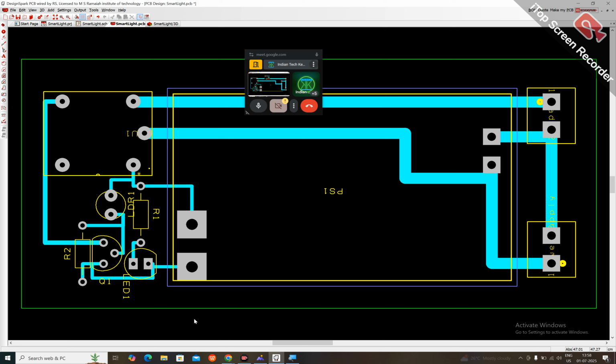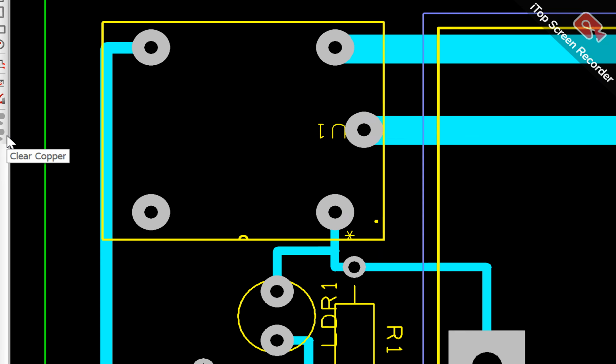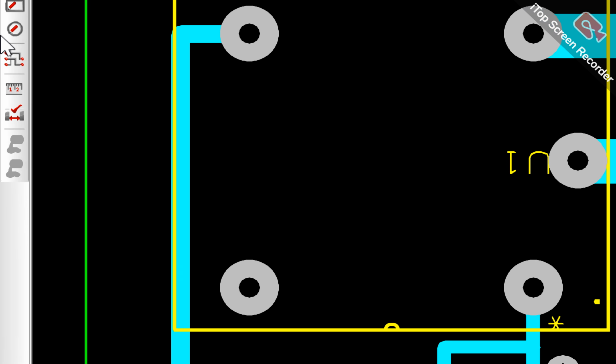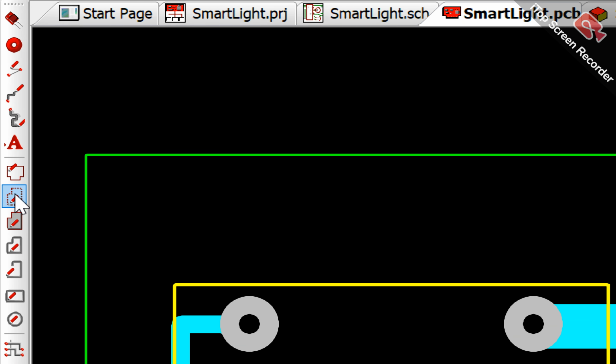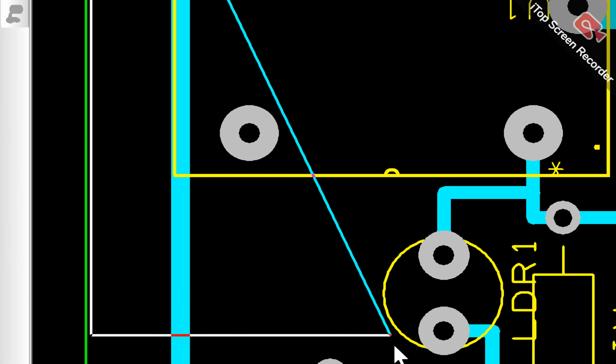Okay. Next thing is, I was informing you regarding the copper pour. So for copper pour, guys, you have to use one option, see, you can observe here there is an option called add area for copper pour. So I'll give some space and I'll add it.